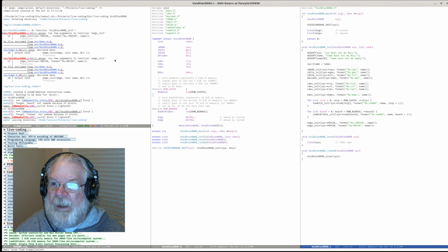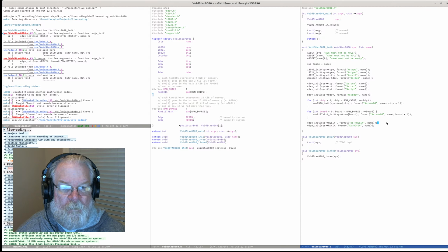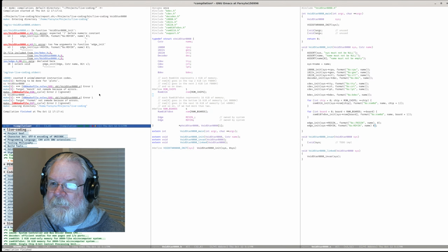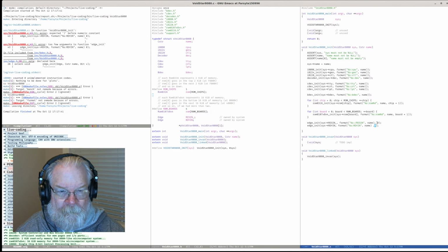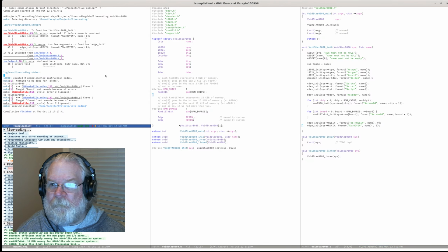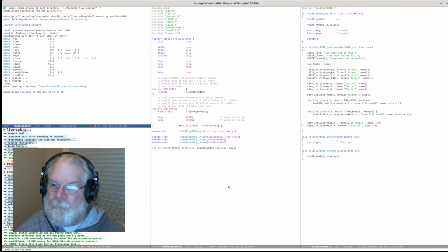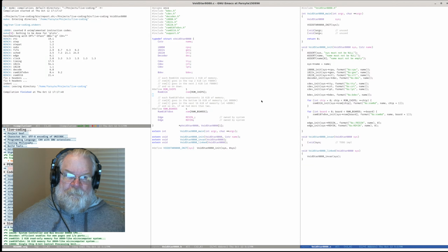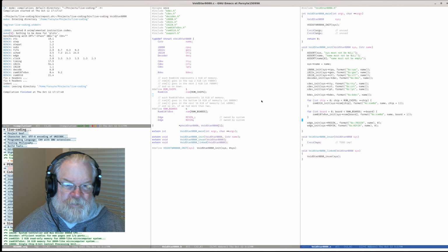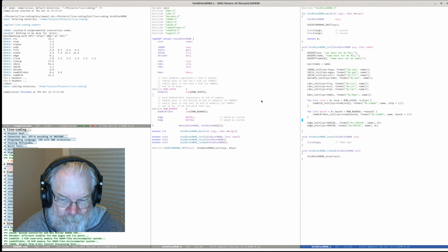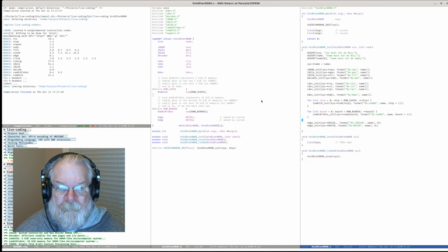And we don't actually have edge. Oh, edge in it, too few arguments, right. So at power up, reset in is going to start low, and ready in is going to start low. So power on reset for our systems always starts with reset and ready low, and we're going to bring reset high and ready high manually.